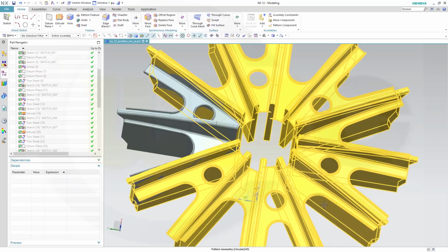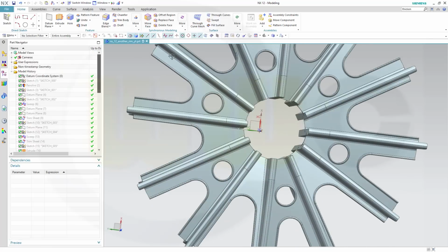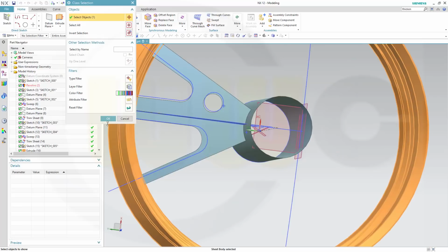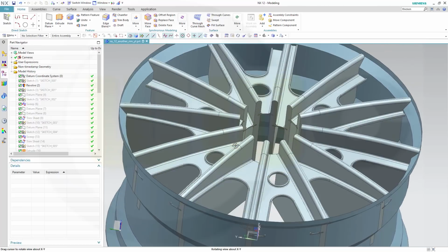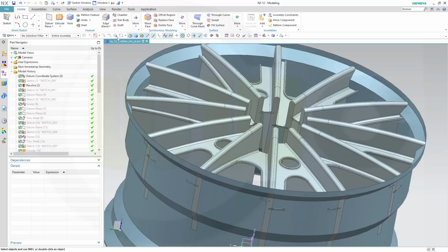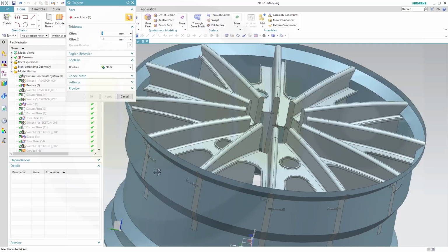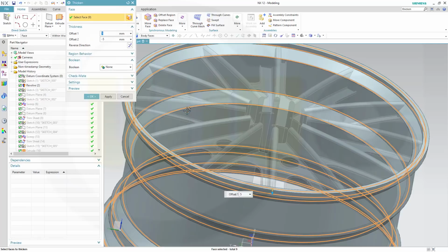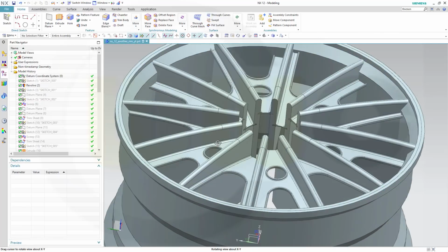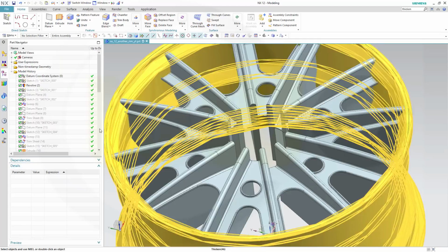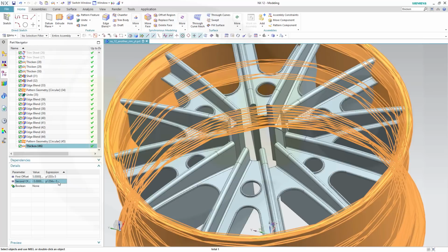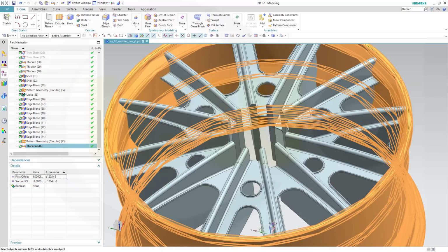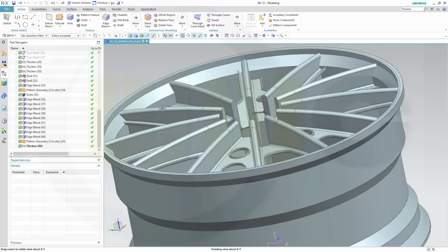Okay, now I want to show my first revolve. This one. Okay. And give it some thickness. So go for more, thicken, this one, 5 on both sides, okay. Maybe, just maybe, not 5 on both sides, maybe just -3 on this side. Yeah, looks good.